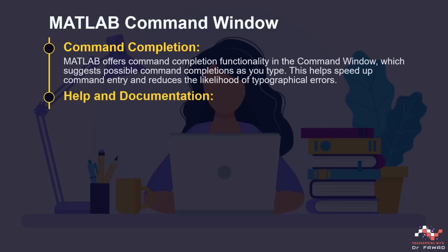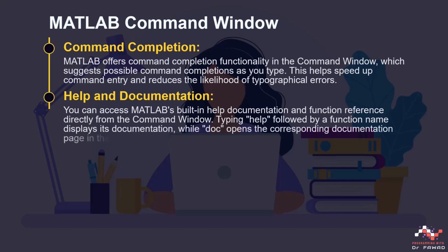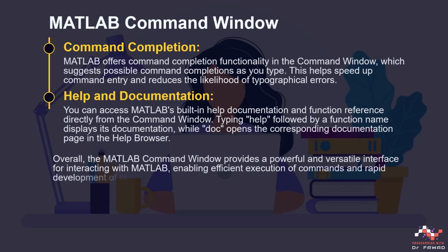6. Help and documentation. You can access MATLAB's built-in help documentation and function references directly from the command window. Type help followed by the function name and it will display its documentation, while doc opens the corresponding documentation page in the help browser. Overall, the MATLAB command window provides a powerful and versatile interface for interacting with MATLAB, enabling efficient execution of commands and rapid development of MATLAB code and scripts.